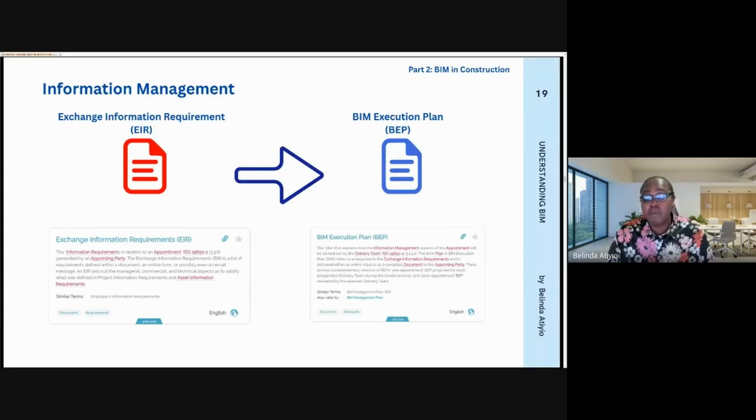And this BIM execution plan is a live document. It's not a one-time document. You create it before you go into design. You update it when you go into construction. It's also updated when it is handover time and then handed over to the client or the client's facility manager, because it contains a lot of documents and it also contains the life cycle of the project. So the BIM execution plan is very important.